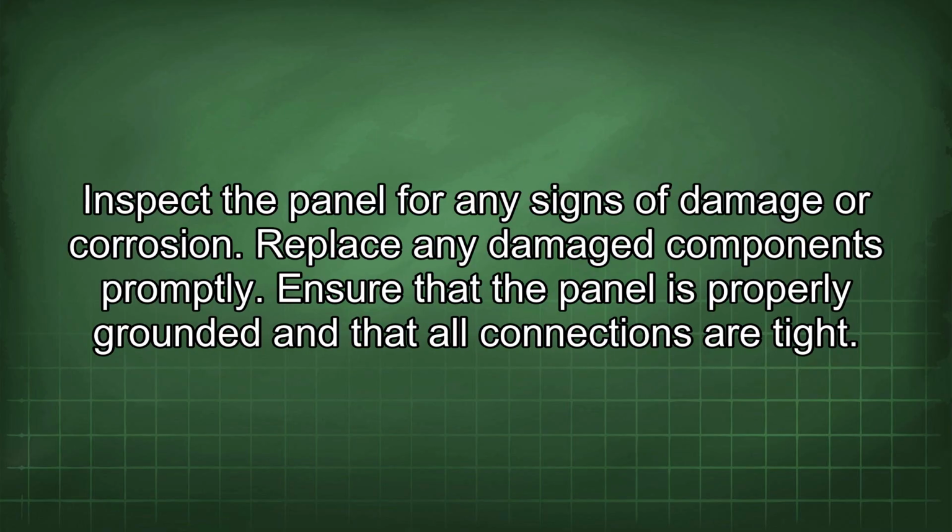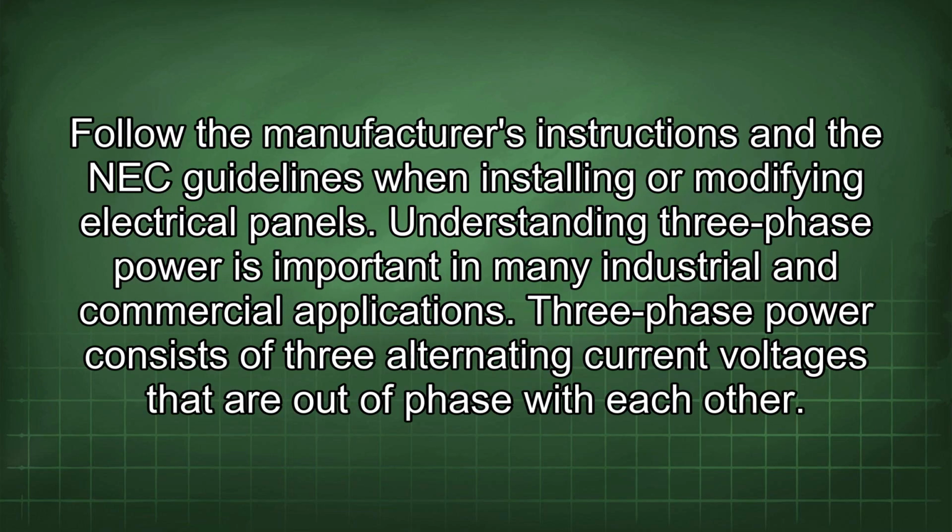Inspect the panel for any signs of damage or corrosion. Replace any damaged components promptly. Ensure that the panel is properly grounded and that all connections are tight. Follow the manufacturer's instructions and the NEC guidelines when installing or modifying electrical panels.